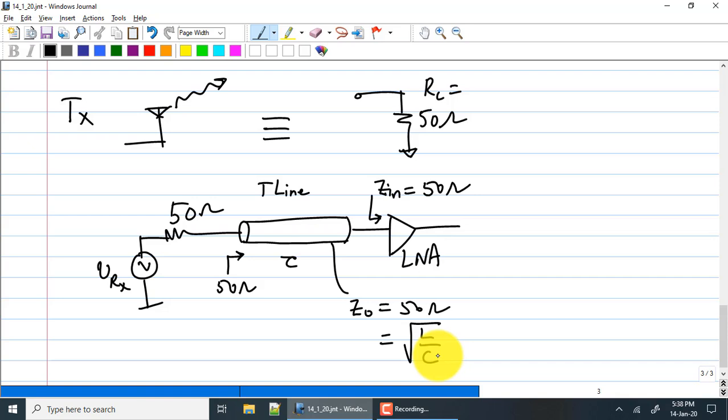Then you see that your LNA also needs to present 50 ohms. So you need to figure out a way to design your amplifier circuit. Unlike every other amplifier that you have seen, which normally has high input impedance or very low input impedance such as common gate, you now need a circuit that has something in between. It requires 50 ohms. Whether it's a common source, common gate, or source follower, whatever you choose, it better have a 50 ohm input impedance. Otherwise it's not going to work well. But your circuit itself may work very well when the impedance is not 50 ohms, but maybe 100 ohms. What will you do then?